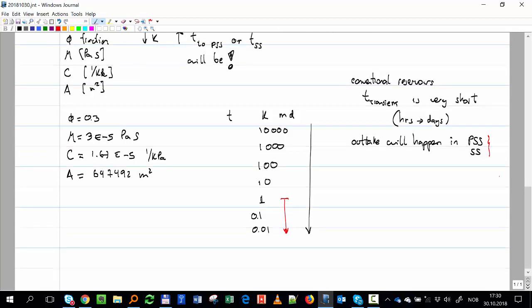Okay, so when the well is in pseudo steady state, I can remove time out of the picture. I can remove time and use reservoir pressure instead. Reservoir pressure will give me an indication of time. When it goes down, it is just because more time has passed, right? And just use PR.